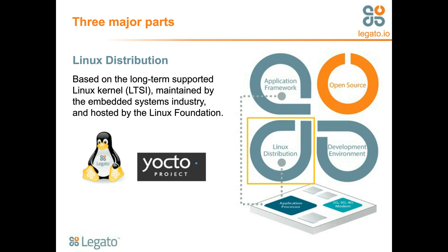The Yocto project ports and validates a huge collection of kernels and user space packages on many CPU architectures, and you now have a choice of several tested mainline kernel versions to use with any given version of Yocto, and you have the option to use a long-term supported kernel, for which critical fixes are backported by the Linux Foundation for years. So you don't have to worry about porting your drivers to a new kernel or backporting critical fixes yourself every few months to stay safe from newly discovered security holes.